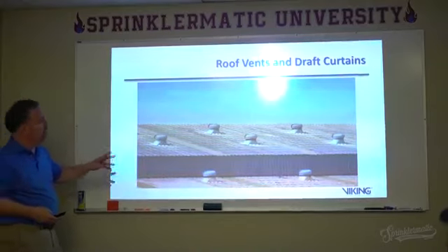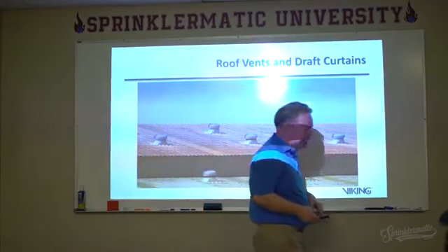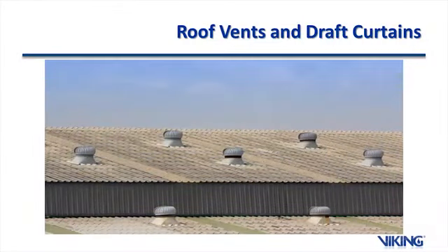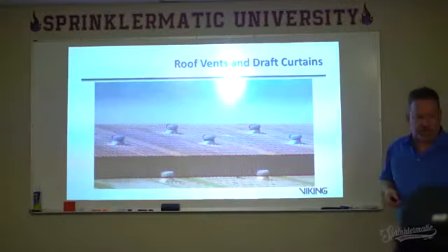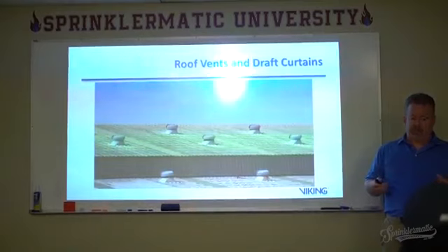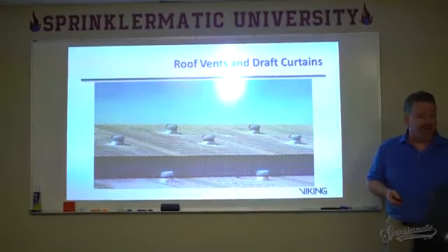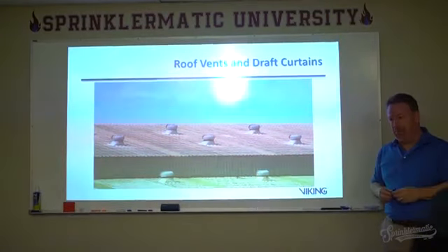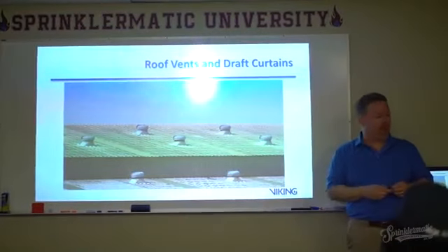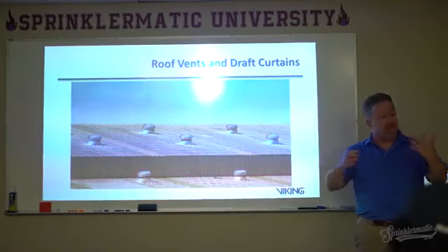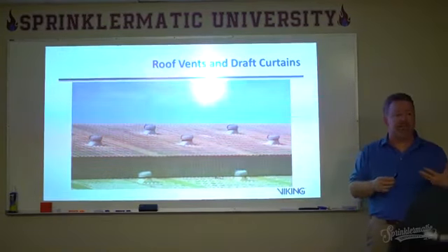Chapter 12 has a couple of things to say about what goes on at the ceiling line. In other words, we don't like vents. We don't like roof vents in NFPA 13 when it comes to storage protection. Why? What do roof vents do? They vent the hot air. And what do we need? We need the hot air to activate our sprinklers. So if vents are operating and taking away that hot air, we have a tendency to have sprinklers perhaps go off where we didn't intend them to.